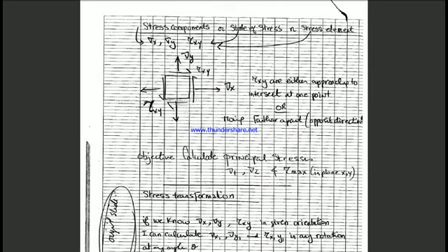as we said before, we have the stress components sigma x, sigma y, and tau xy, and our objective is to calculate the principal stresses sigma 1, sigma 2, and tau maximum in plane xy. So sigma x, sigma y, and tau xy are stress components, state of stress or stress element, and the distributions look like this. Tau xy are either approaching one another, as you see here, or getting further apart from one another, like in this case and this case here.